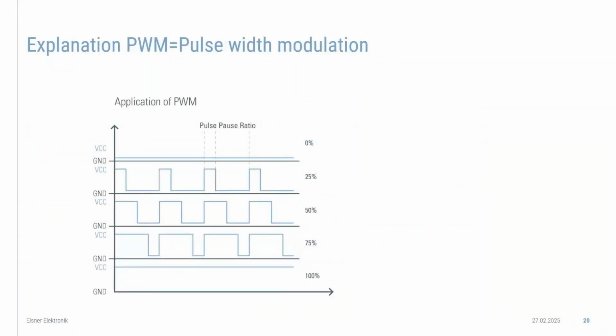As announced, now we will have a look at the pulse width modulation. The KNX heating actuator receives the actuating variable from the continuous controller and converts it into a corresponding pulse width modulation signal. In the following, we will take a look at how pulse width modulation works.